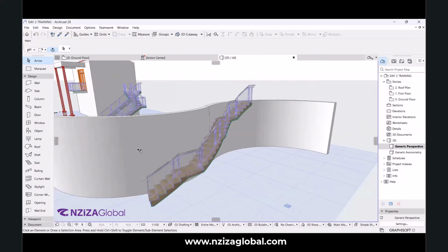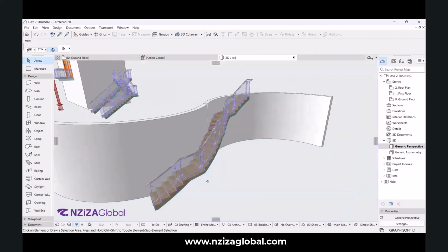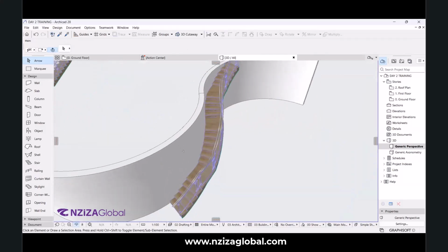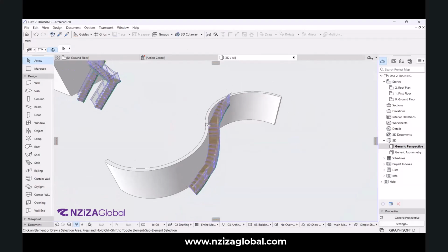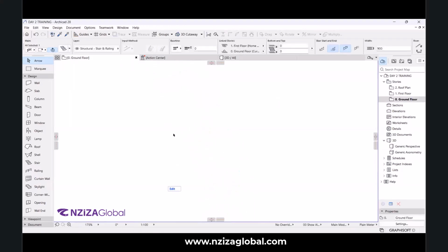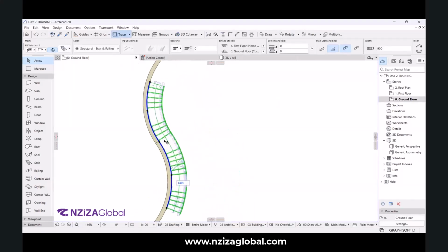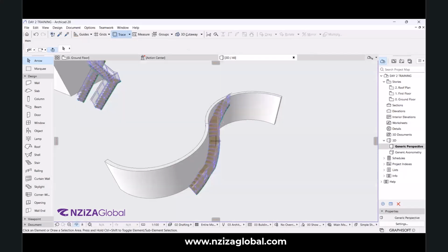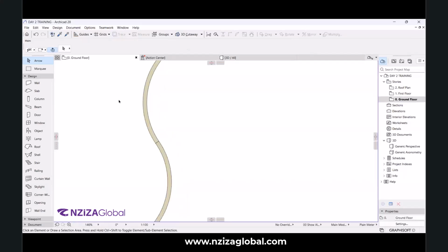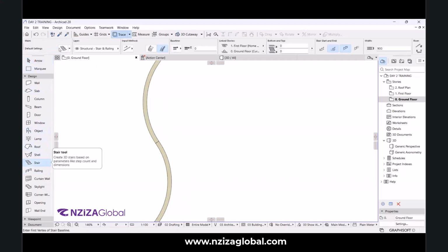Before I give you time to revise, these landings, too many landings, have made it go the wrong way. It is caused by the type of stair I selected before drawing. I will delete this one. And I will go into stair setting.